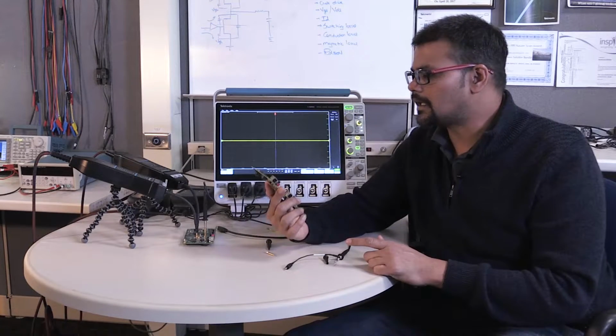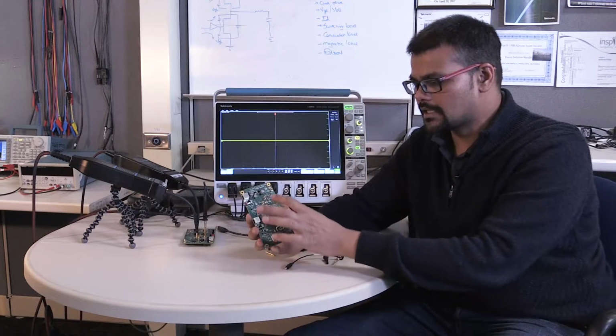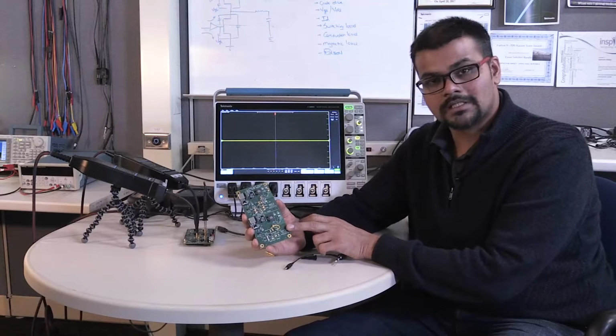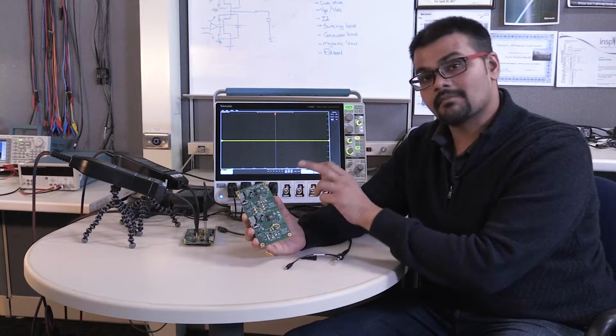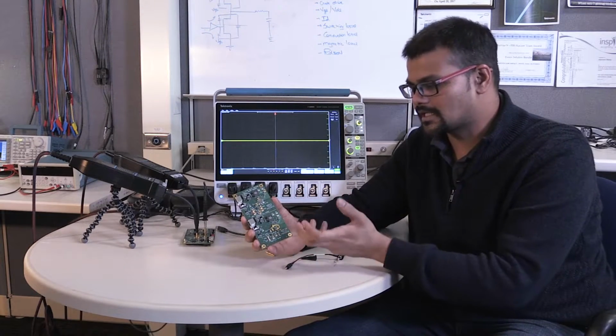So this is a GaN half bridge board. It's based on a GaN product. It's a half bridge, and we have two of those circuits on top and the bottom. They're identical circuits. They're isolated from each other. The one on the top has MMCX connectors on it. The one on the bottom has square pins, so we can compare between those connectors and see the effects of those connectors.